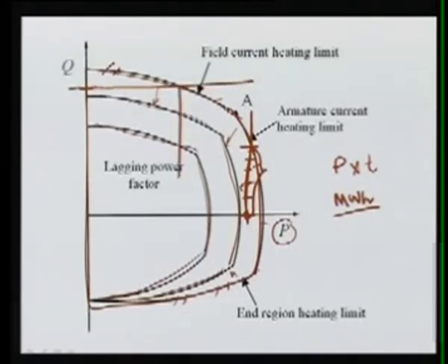Your real power will be coming here. So this point means your real power is now limited, which means you cannot generate more than this power for this reactive power. This is your reactive power requirement. What happens? You cannot generate more than that real power, and if you are going to get money only for this P, you are losing the opportunity in this market.